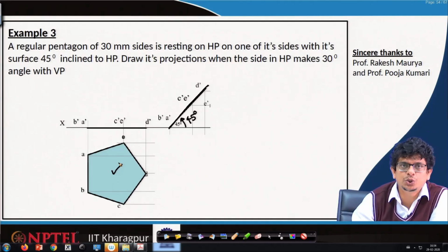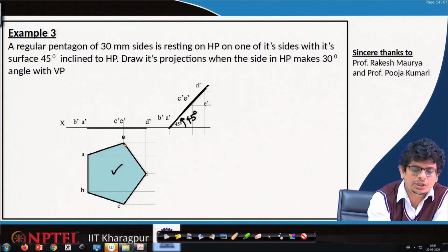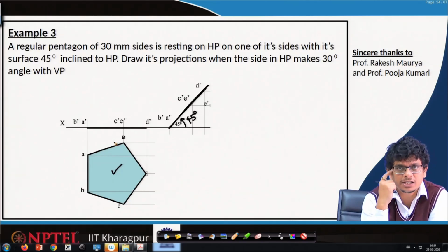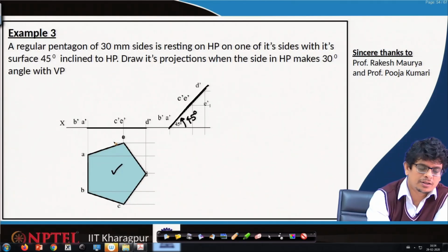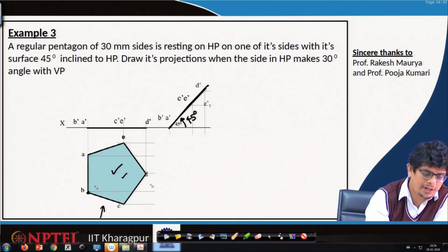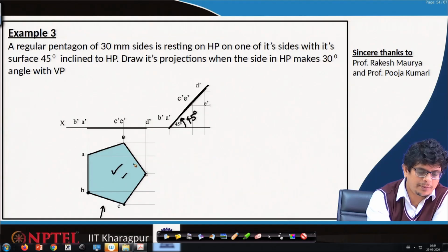By rotating it suitably, one of the edges we can make 45 degrees or 30 degrees, 60 degrees and so on. So, top view it will be like that. If we are looking from front view, it will be just a line where B point, C point, D point map to B prime, C prime, D prime respectively.